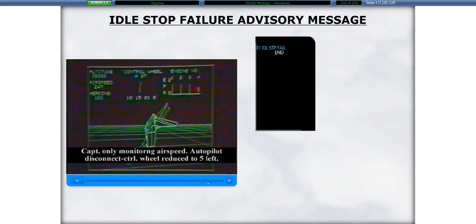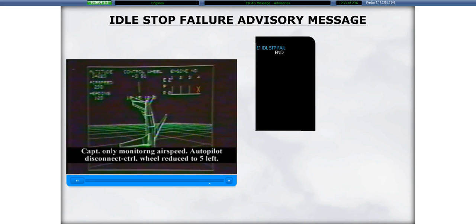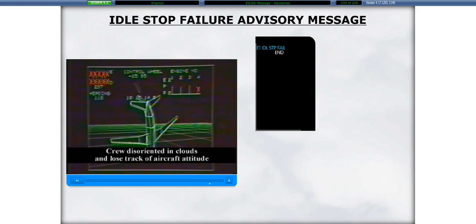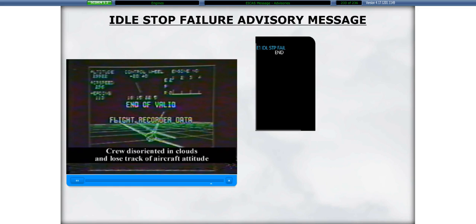Symptoms may include multiple system problems such as generators dropping offline, low engine oil pressure, unexplained airplane attitude changes, and significant differences between primary parameters from one engine to the next. If asymmetric thrust is suspected, the pilot must be prepared to make immediate rudder or trim inputs to avoid an uncommanded aircraft roll. The first response must be to make the appropriate rudder input or trim adjustment. Disconnecting the autopilot without appropriate control input or trim adjustments may result in a rapid roll maneuver.